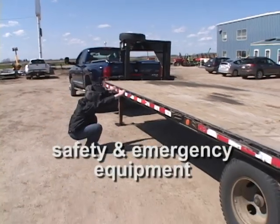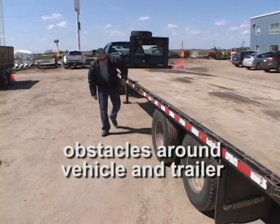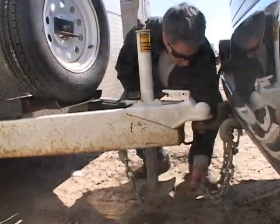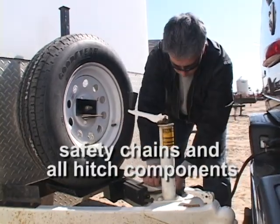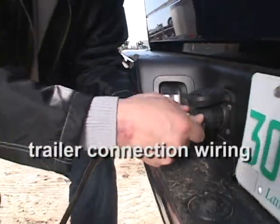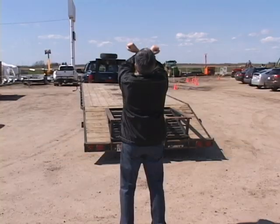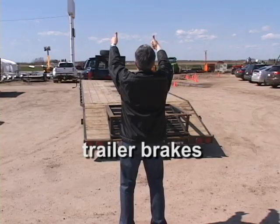Check safety and emergency equipment. Check for obstacles around vehicle and trailer. Inspect safety chains. Inspect all hitch components. Check that the wiring is properly connected to the tow vehicle. Check the brakes on the tow vehicle and trailer.